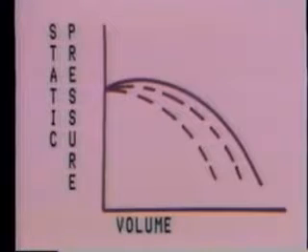Care must be exercised in selecting the fan. It is important that the fan can be throttled to the near minimum flow required without becoming unstable. Systems that can be throttled to near shutoff must often be equipped with a fan bypass to permit a minimum flow through the fan at all times.